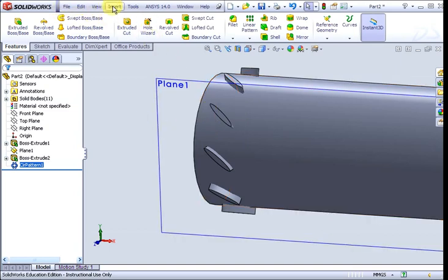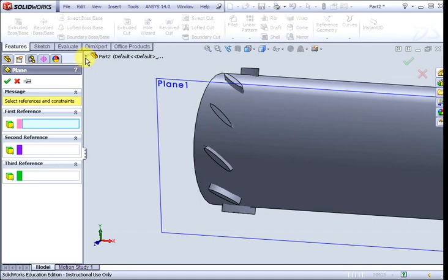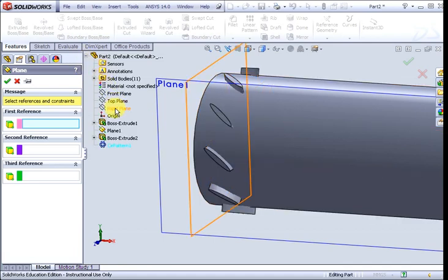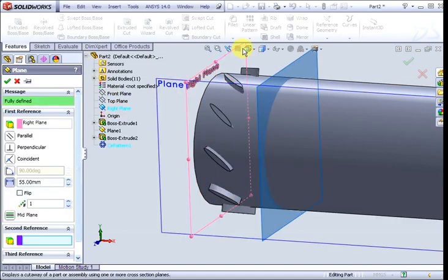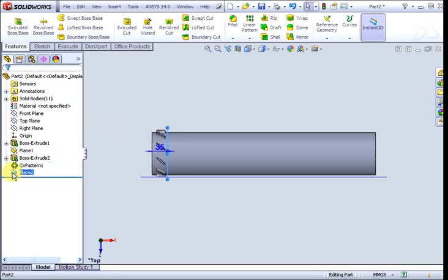So we have to define first the reference. So the reference geometry, we have a plane. This time the plane will be the right plane. We see again from top. Okay, so we have to move it a little bit closer. Okay, that's enough. It is around 35 mm, so we have to remember this number when we do the injector later on. So this is good enough for the plane, 35 mm. Now we draw the sketch on this plane.